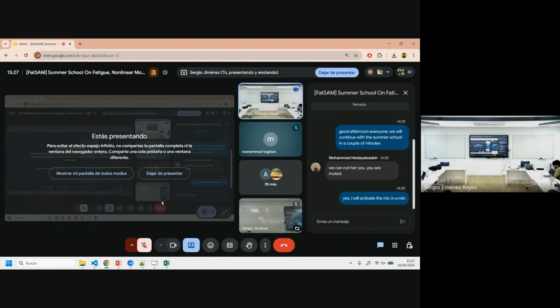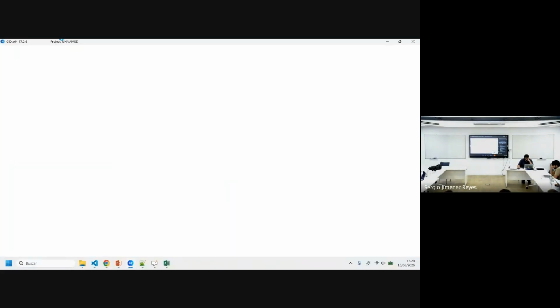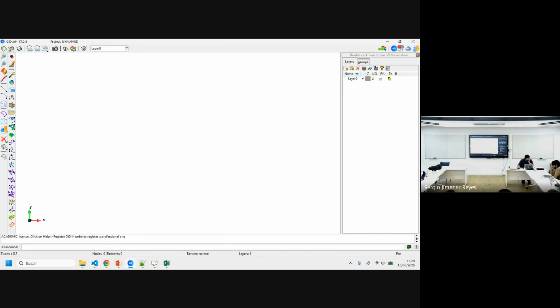Well, if you want to import an IGS, the first one, then you click on the IGS file of the segment and it will open. If I'm not wrong, the issue with the file that I sent you is that I used AutoCAD, and so some of the lines, even though it seems that they intersect, they do not. So in order to create the surface, you will see that you will find some problems. So let me just do it and let me show you how to solve that.